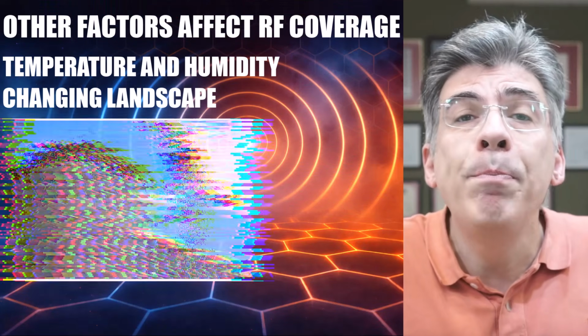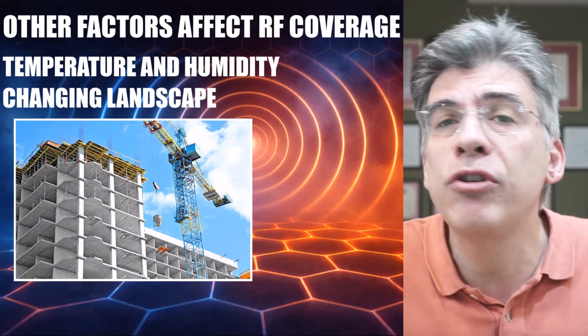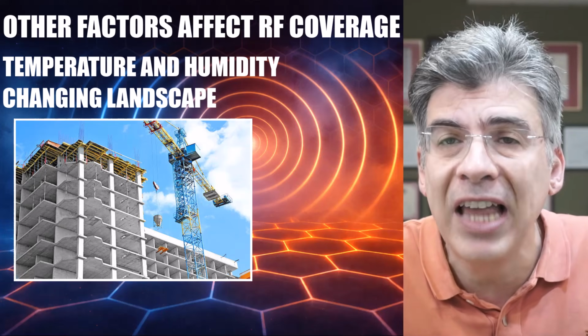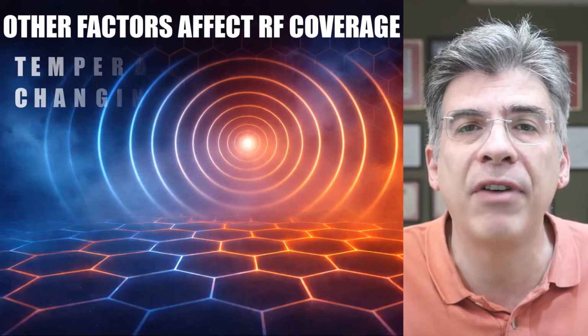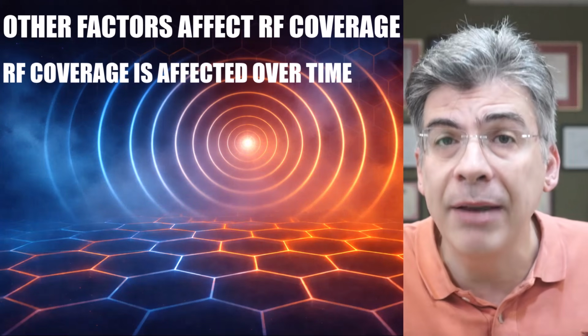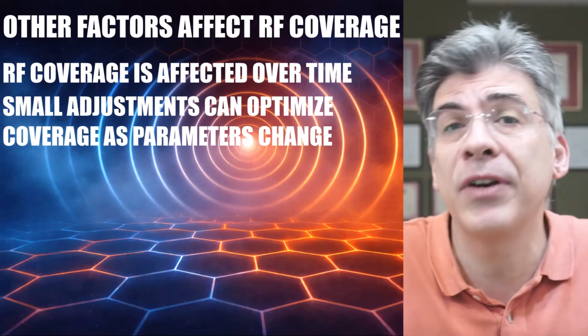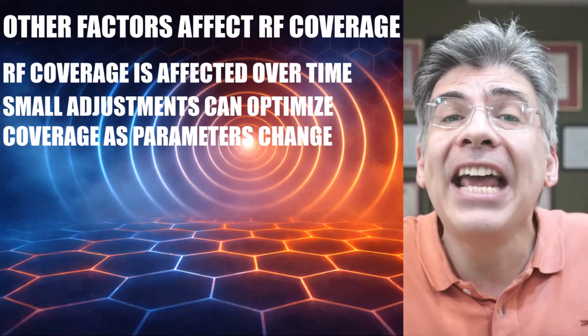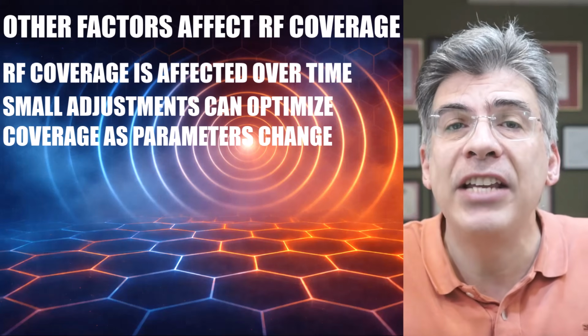Or a new building is built near a cellular base station, and this changes the whole distribution of RF signals due to reflections and refractions, and this represents a more permanent change in the environment. All of these changes affect RF coverage over time, and small adjustments to the antenna, its tilt, its frequency range, its power output, can optimize coverage as these parameters change around it.